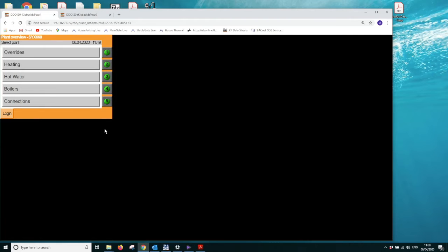And so we end up in a situation where the Optimiser can calculate a warming up rate, which is based upon the number of degrees C the temperature in the space will increase in an hour.